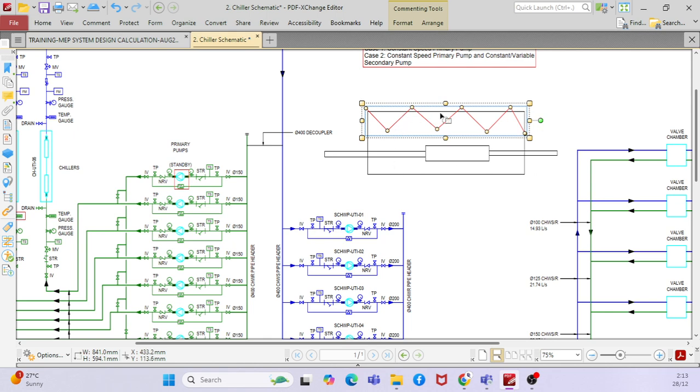So basically, what you're trying to say, in a closed circuit system, you would generally have your entire evaporator, condenser, all of the typical refrigeration cycle components within one loop itself, so that you have only one set of line. I mean, two sets of chilled water lines, with the supply coming from one side, and on the opposite side the return coming back to the evaporator.